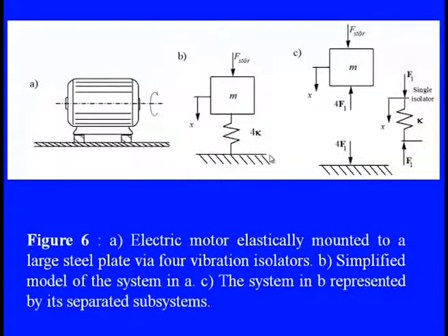When we resolve the free body diagram according to the forces acting on the system, we have the excitation force F applied on top, and the restoring forces which come out due to the spring connection. Equal and opposite spring forces act on the mass as well as on the foundation. The next diagram gives a clear representation of the spring and the restoring forces being balanced at both ends of the springs.